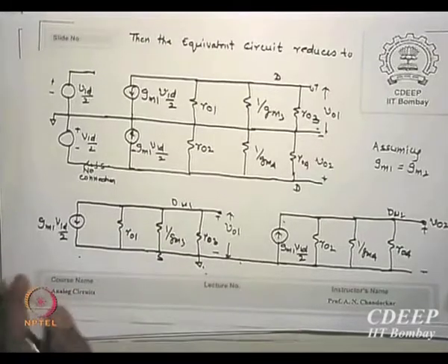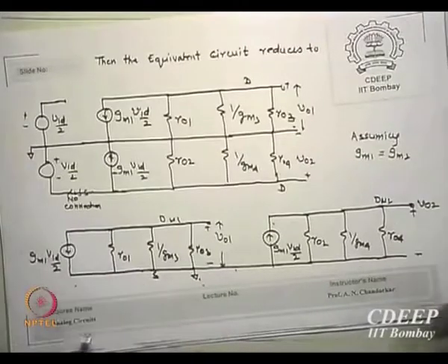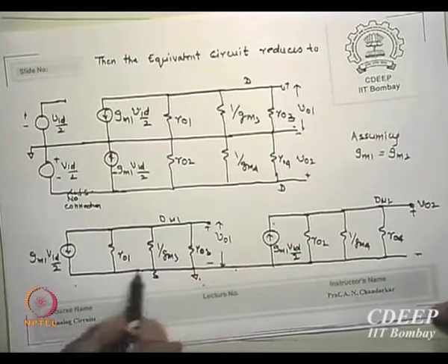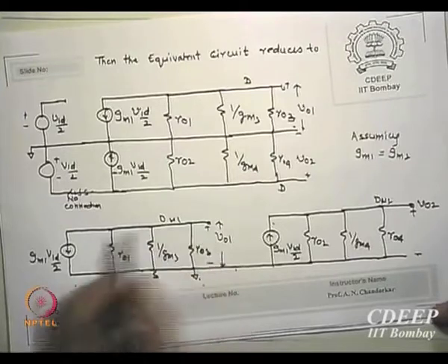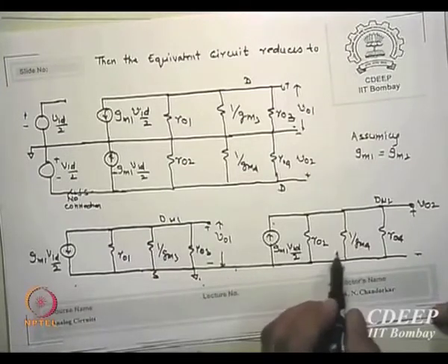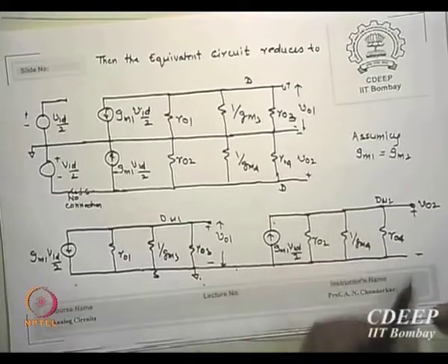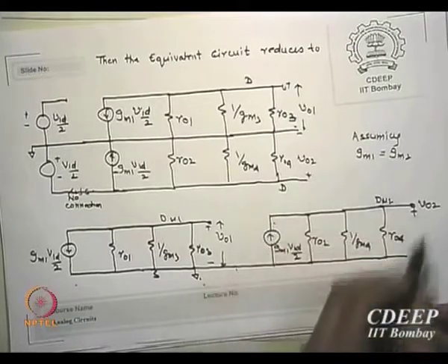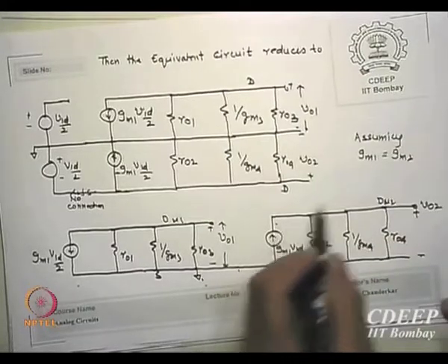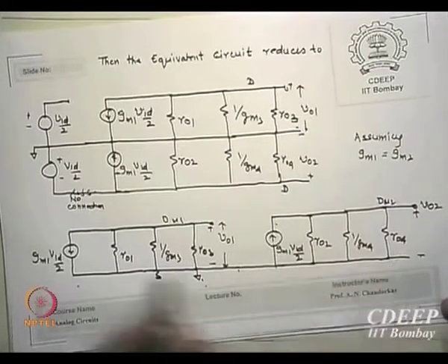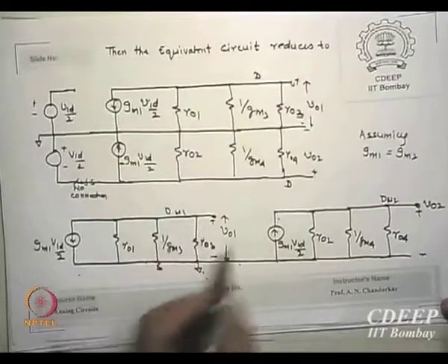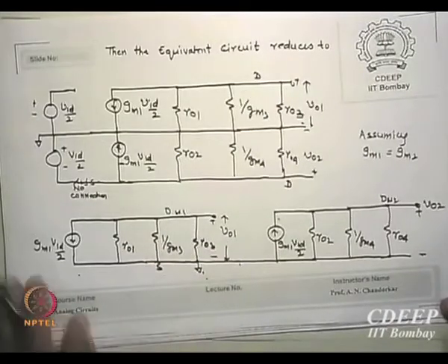Okay, opposite sign. So if I have now these two circuits, what do I calculate? VO1 and VO2. How much is VO1? Quickly tell me. Minus GM times this load, and this is plus GM times this load. This is plus, the sign is this way. This is plus GM times this load is the output, minus GM times this load is the output, is VO1. Is that clear? So if I calculate both of these, which I did, you solve yourself again.